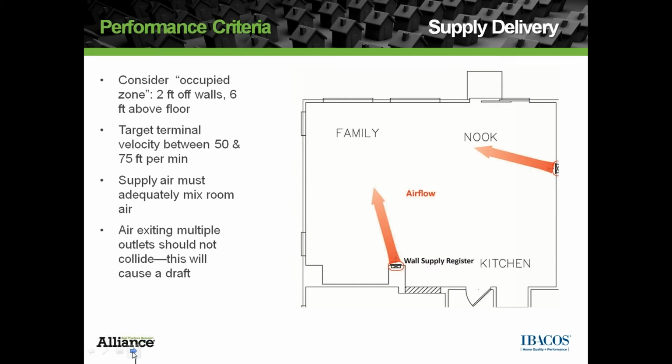All right, I have one question here. A lot of times when we work with builders, the majority of the time, building officials want to see a supply register accompanied by a return register in the same room to circulate that air in that occupied zone. How do we combat that with some of our building officials when they want to see those scenarios? We're going to talk a lot about the importance of return air strategies later, but there has to be an understanding of how the system works, and it really is comprehensive. It's not one point after another.